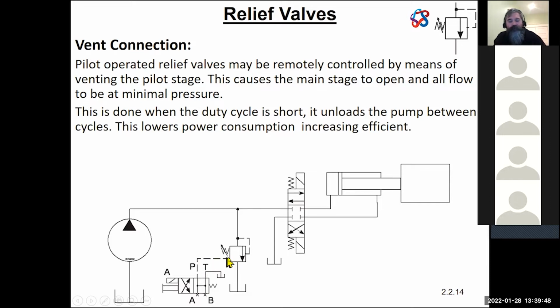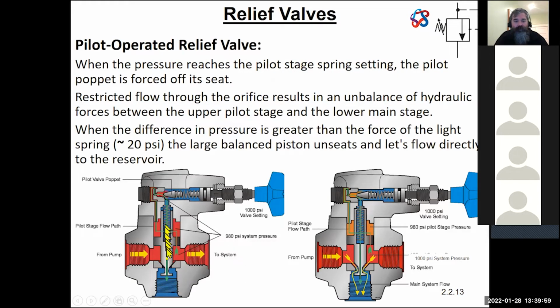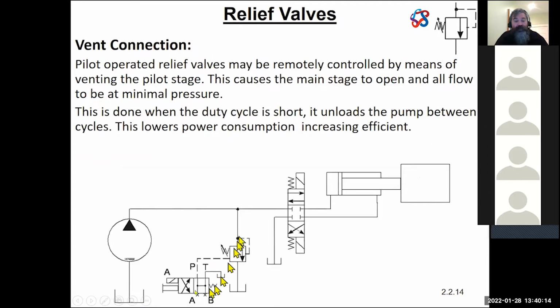there's low pressure here. There's low pressure at this point on the valve. What that means is if there's low pressure there, it's going to allow the main spool to move upwards. It's as if this was cracked, as if the pilot was open. I've got low pressure here, a little bit of fluid allowed to leak out through my system and back to tank. Therefore, in this configuration, all the fluid flow would be dumped. Okay, it wouldn't be allowed to operate.